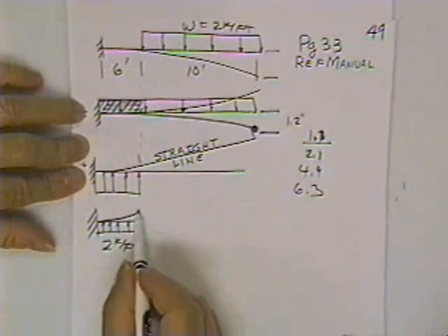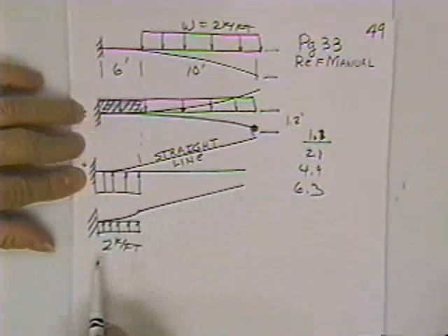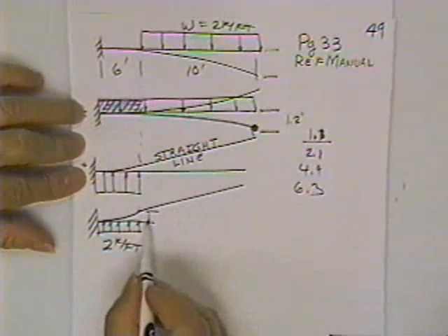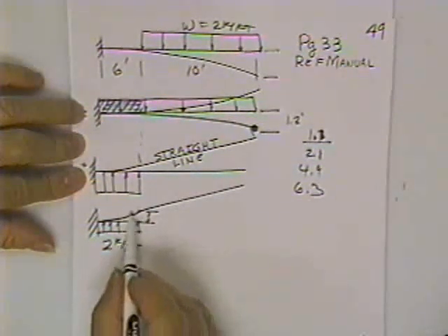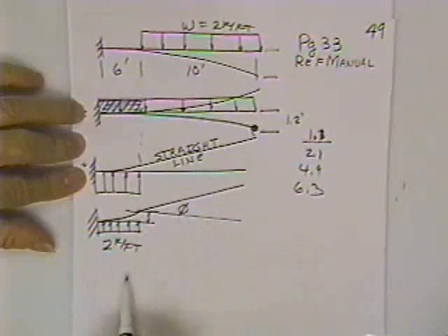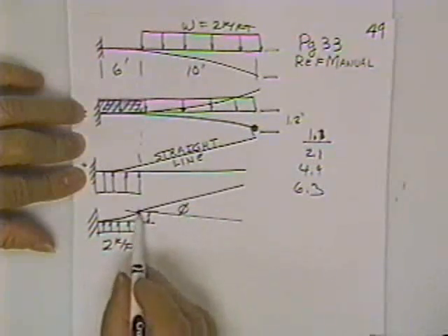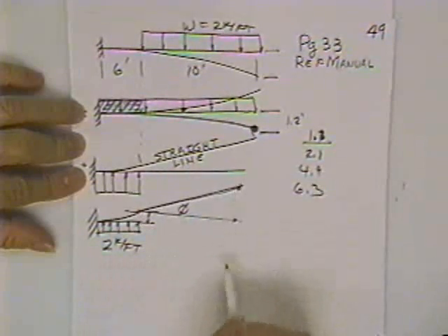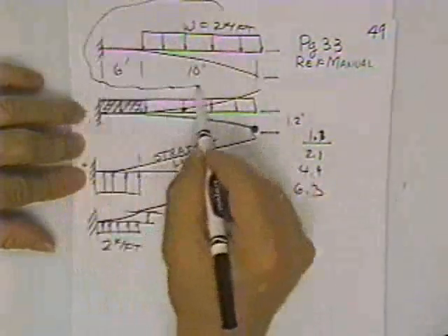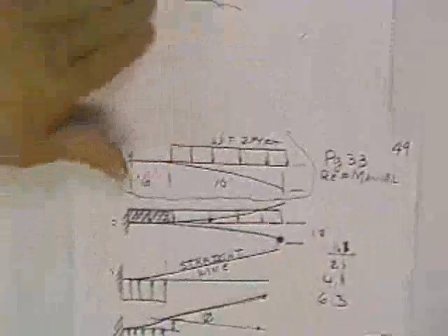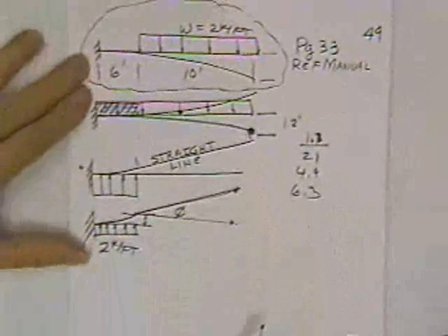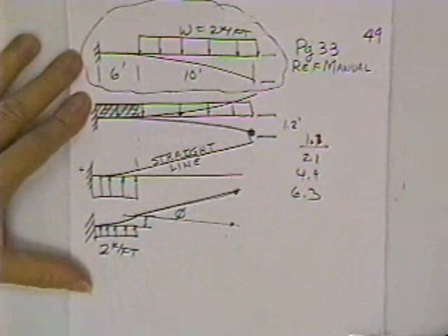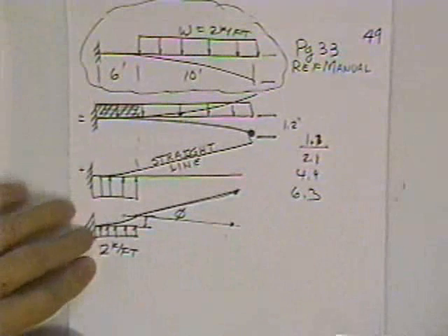Now that beam will move up, and it will also have a slope to it. And you can find how far a beam moves up with a uniform load on it. And you can also find this slope, so you can take away how far the beam itself moves up, and then knowing the slope, you take off this much more, and you'll have this case. So what you really are going to do is piece together, cobble together an answer out of the stock sets of answers that he has.